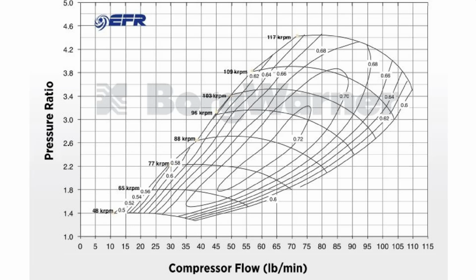So the region on the left side of this is called the surge line, and anything that operates in this region, we're in danger of causing turbo surge, which will cause a lot of problems with the turbocharger. It puts a thrust load on the bearing system, and the turbocharger will actually start to disintegrate if we operate in that region too often under load. And then the region on the right is what we call the compressor choke or the stonewall line. And so this can also cause damage to the turbocharger. So we're not supposed to operate in these regions.